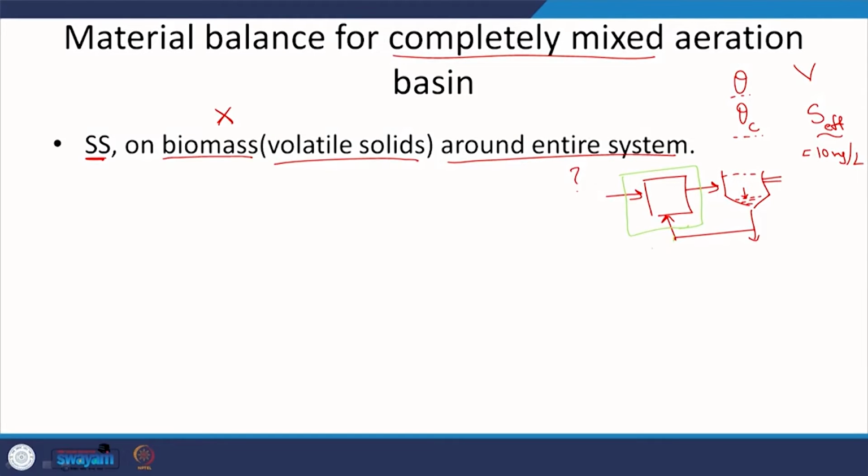So, that will add to some unnecessary complexity. So, to make it simpler, if I choose my particular control volume to be this, right, this is my control volume. Obviously, I need to see to it that, this is wastage. So, what is it that I am just concerned about? Mass coming into the system, mass going out of the system, and mass being wasted from the system. So, these are the three aspects, and I do not really care what is happening within the system other than the reactions. Whatever flows coming, recycle flows inside the system, I am not really concerned with it. So, this is my control volume which we just defined, right.